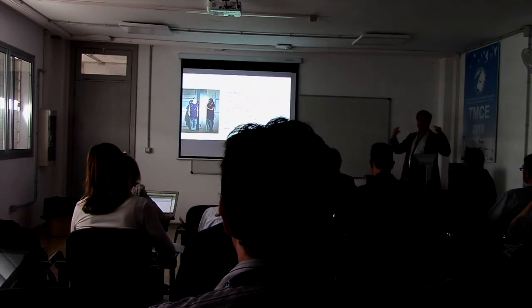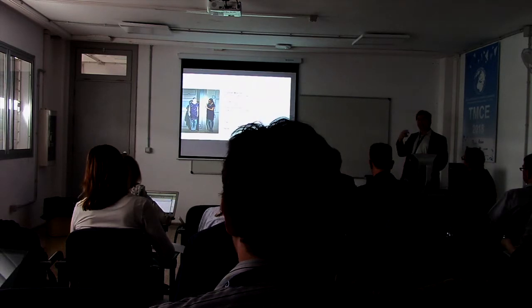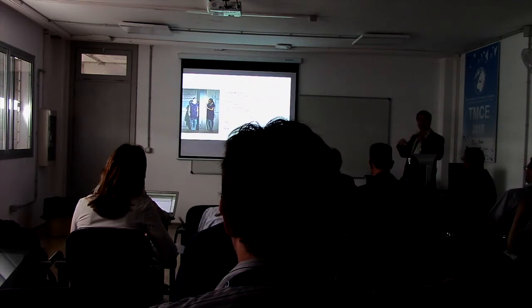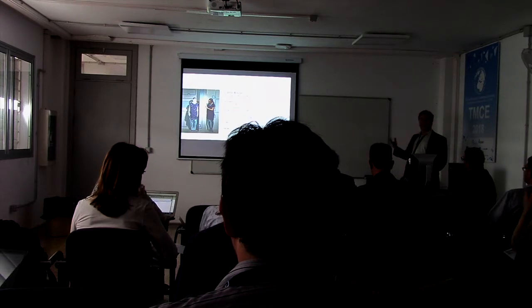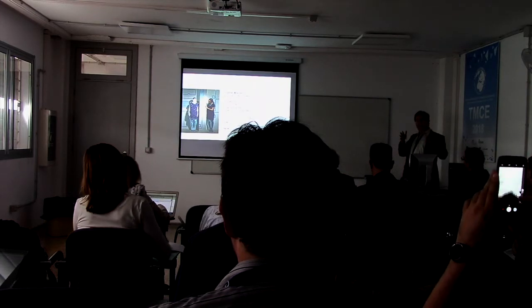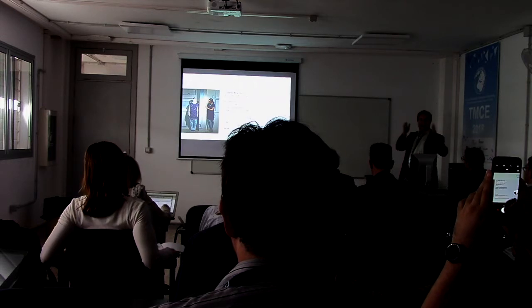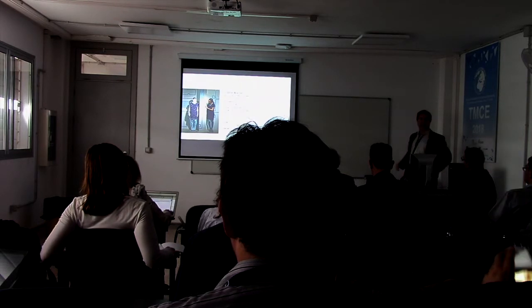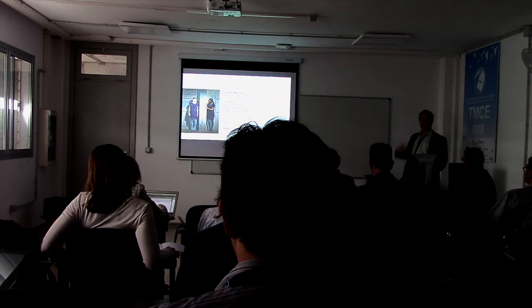Data is more than measurements. It also has to include the information about what the reason for a malfunction was, and to use something like artificial intelligence you need a lot of defined situations where the system can learn. So right now we follow more the approach from the physical side: we simulate some dedicated failures and create some patterns, and then we classify the measured curves with these predefined error patterns.